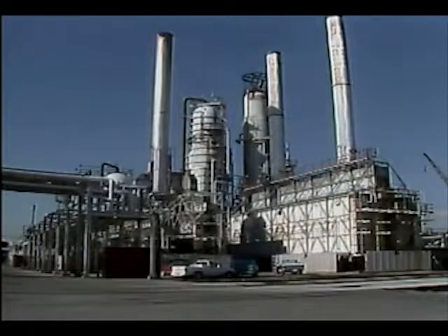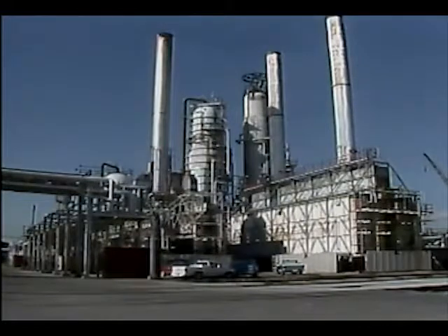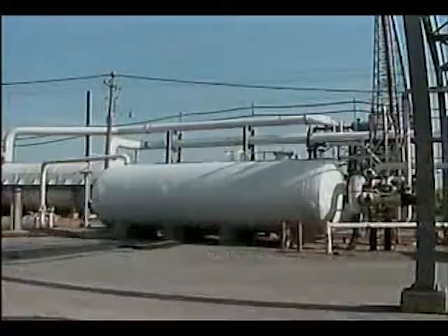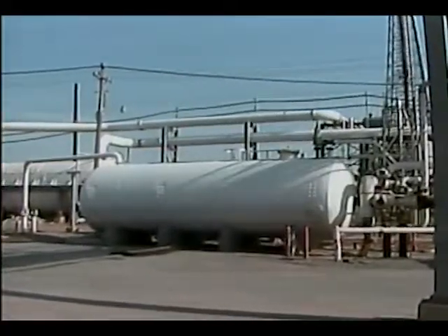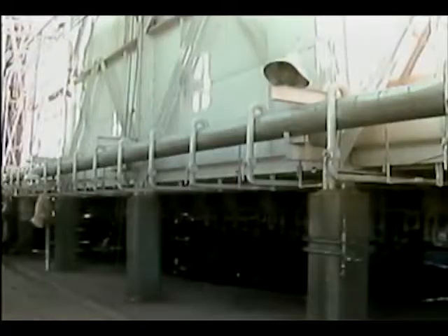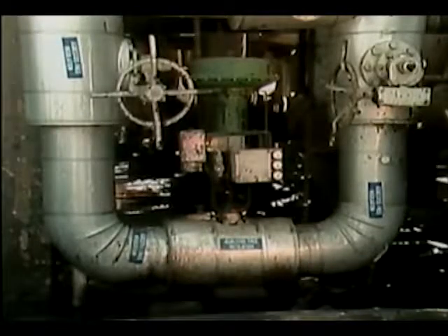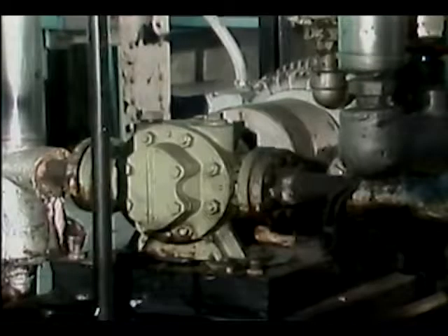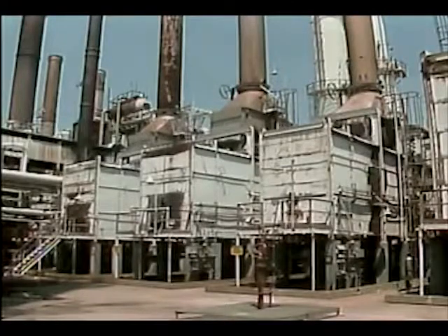Now let's look at some of the basic systems that furnaces rely on for proper operation. One of these is the fuel system, which delivers fuel to the furnace. A typical fuel system includes fuel lines and valves that carry the fuel to the burners and control its flow. On furnaces that use oil as a fuel, the fuel system also includes a fuel pump. Furnaces also need air systems. An air system is needed because the burners in a furnace mix air with fuel for combustion.